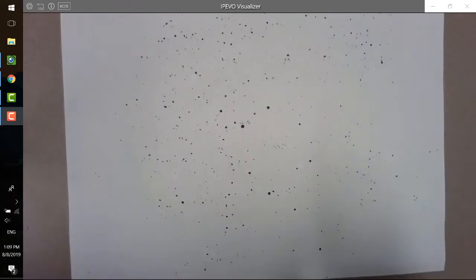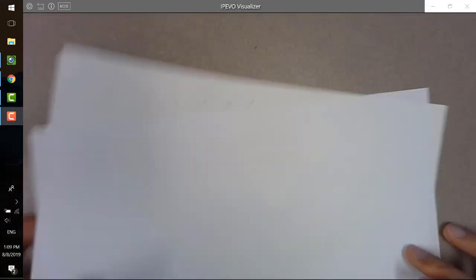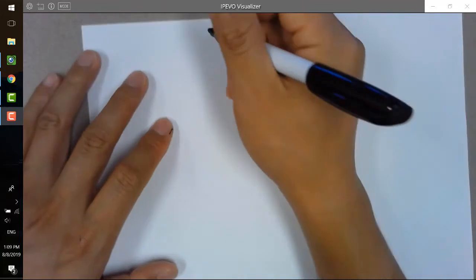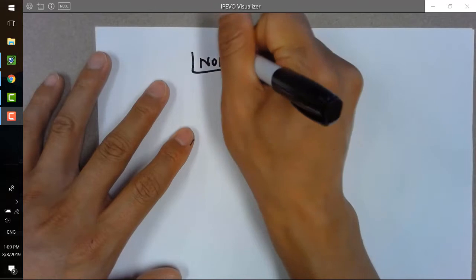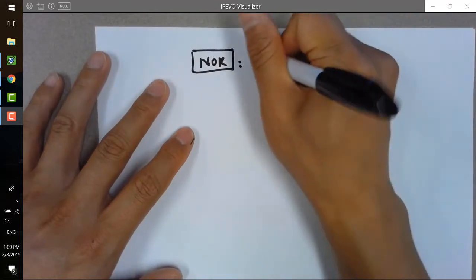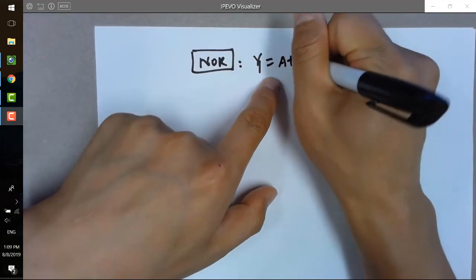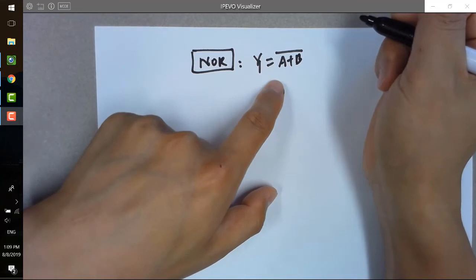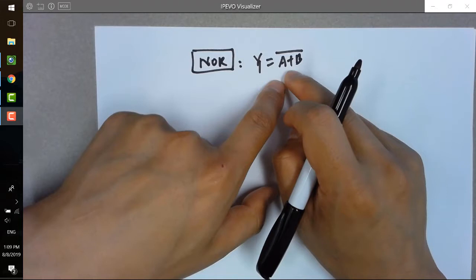Okay. So we have NOT and OR, and now we need a NOR gate. So use a NAND gate to make a NOR gate. How to do that? We know the logic for a NOR gate is (A OR B) NOT. And there's no NAND or AND logic at all here.